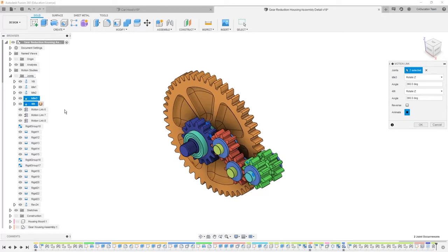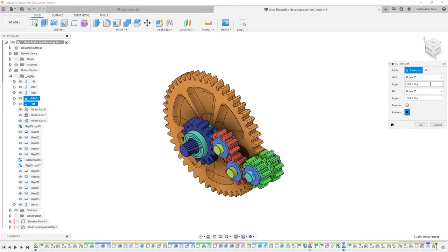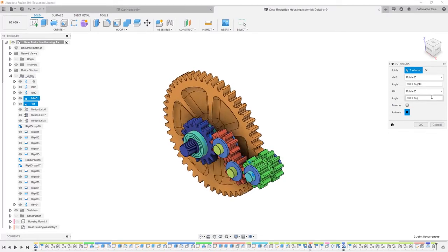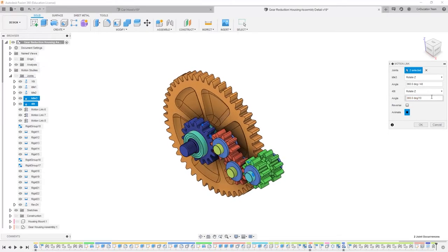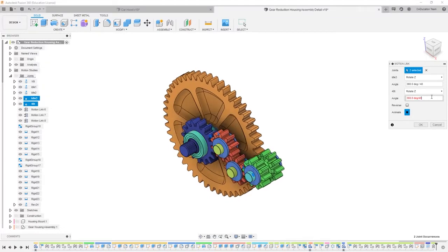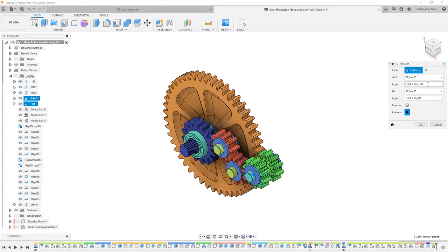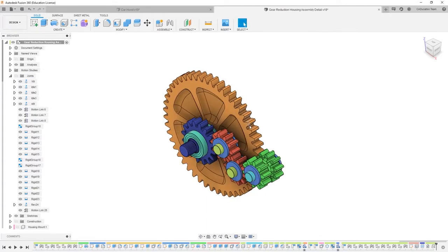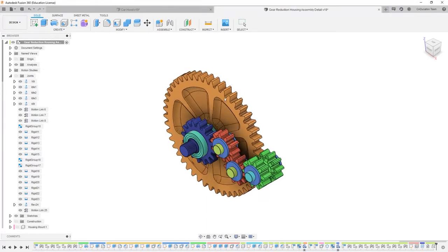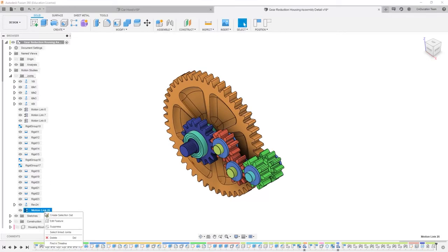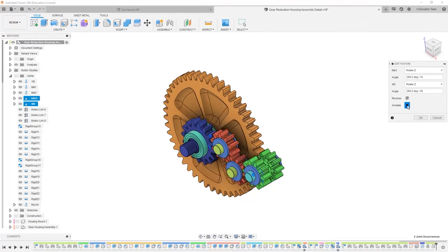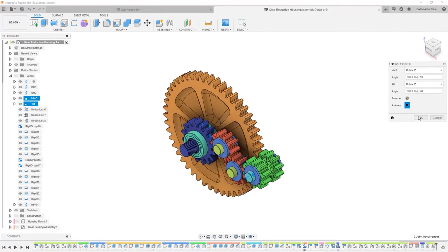In Fusion 360, however, you assemble components with a joint to describe the desired motion. You pick a joint based on its degrees of freedom, and you give it a point that will align to the components. Even better, there are things called as-built joints that make use of the design location of components. This makes the selection process even easier. This will start to make sense once we work through some examples, but it is a very logical process once you break the thought process of having to apply 3 or 4 mates to put components together.